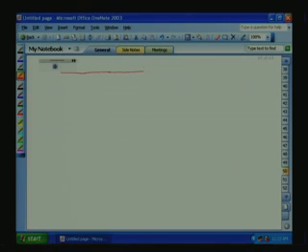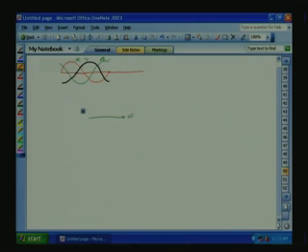When the machine is excited with three sinusoidal currents, let us say RYB or ABC, we know that there will be an air gap flux tracing a circle, and the speed is omega s, the synchronous frequency.